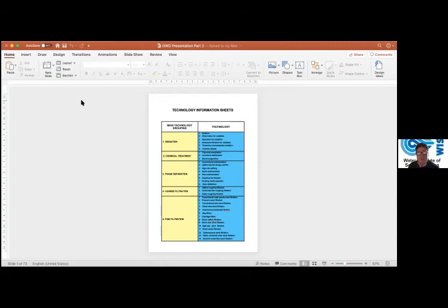Yes, so basically in terms of the process configurations that you can use, your main processes would either be ozone plus granular activated carbon, which normally is biologically activated carbon, BAC, followed by GAC, or you can go the reverse osmosis route, RO, and then normally an advanced oxidation process is used as well for finally causing oxidation or destruction of these very low concentration organic substances.